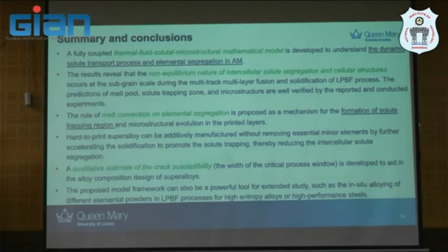So we call it in situ alloying. You alloy A and B, it will be AB or ABC, which a lot of studies do, especially in the high entropy alloy community. They mix 4 or 5 together and blend it under the beam. So this is probably a way forward and keeps more opportunity rather than doing atomization all the time.